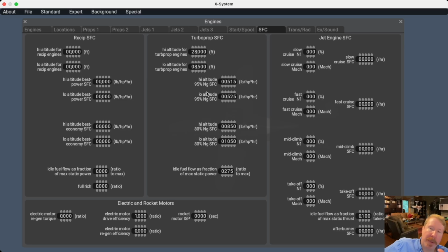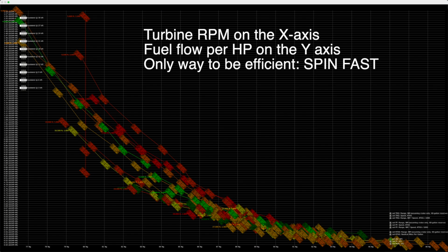Remember the way these turboprops work. A compressor compresses air. That compressed air has to escape the engine, and it escapes the engine by running through a little windmill on its way out. Lucky for us, that windmill is attached to a propeller, hence the propeller spins in this process and pulls the airplane forwards. That's how the turbine works in a Pratt & Whitney. And this engine only works right if that compressor is spinning at maximum RPM. If the compressor slows down, the engine just doesn't work right anymore.